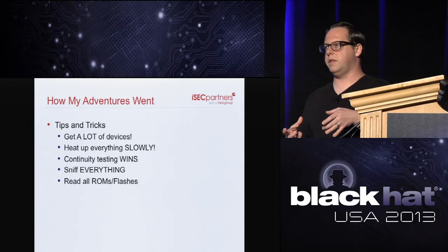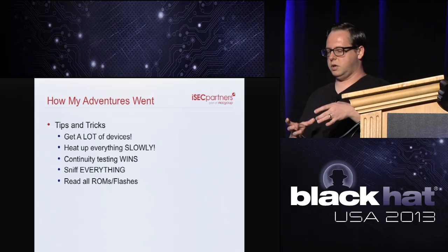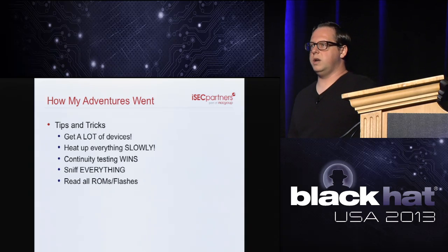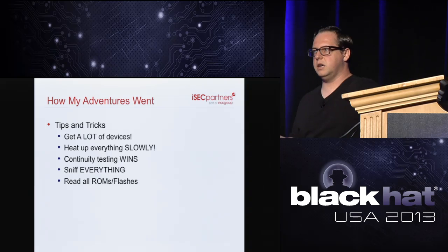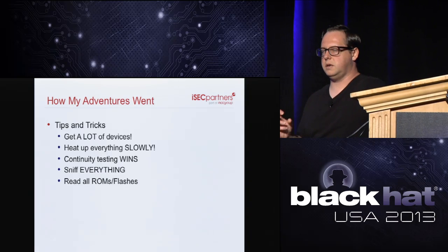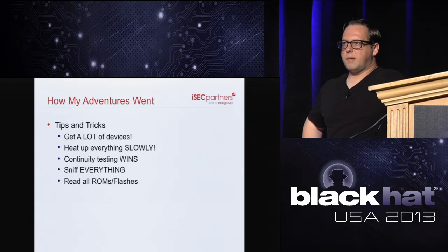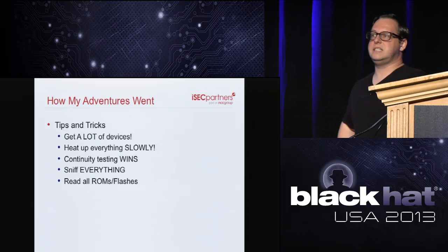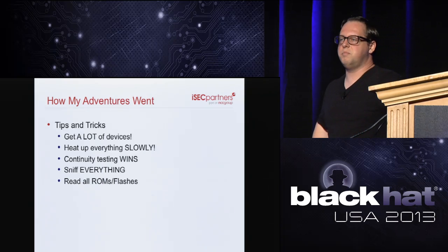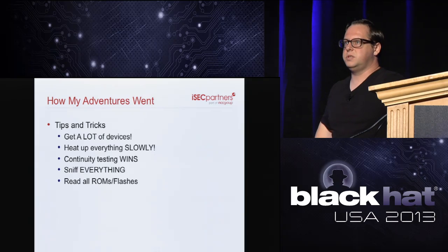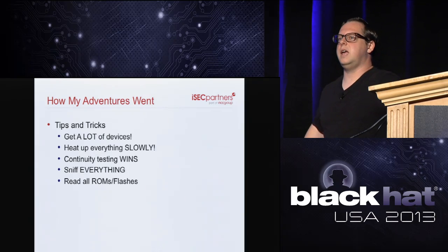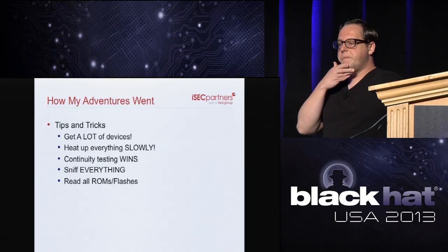So that's all metal that we're going to need to heat up to a correct temperature. Once you're around 180 to 190, then you can crank up your heat gun to around 220 to 250 and do some desoldering. I actually wasn't able to pull the chips off until I got up to around 300 degrees Celsius. So some of the EEs out there might be like, oh, that's awful high, you're going to damage the chip. But I was successfully able to desolder them at that temperature and connect them in.